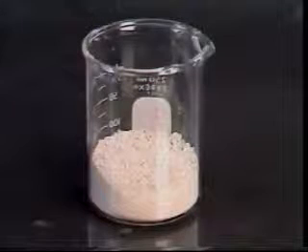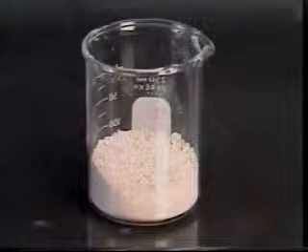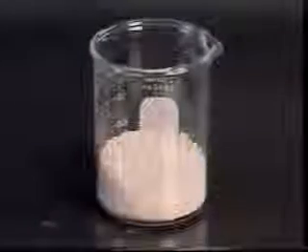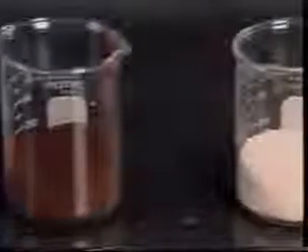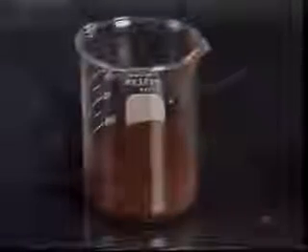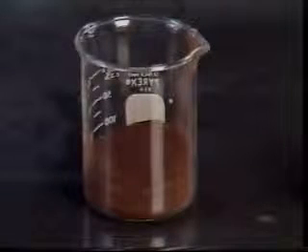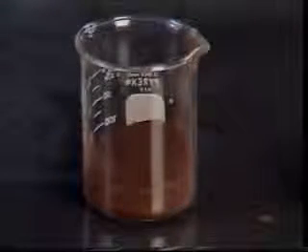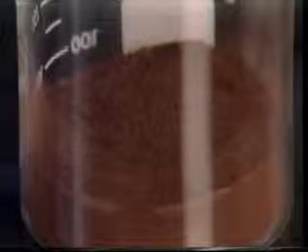It has a specific gravity of 4.5 and can be used to raise mud weights as high as 22 pounds per gallon. Other materials, notably iron compounds, have higher specific gravities, but are abrasive, have a tendency to settle out of the fluid, and have magnetic properties which can interfere with logging methods.